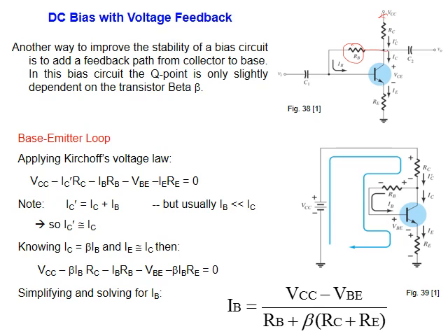And this means that if I come to find the equation for the input circuit, which is on the base, and the output circuit on the collector, see the difference. Now current will flow from VCC through RC. Now RC becomes part of the input circuit, then RB, then the V base emitter drop, then RE.